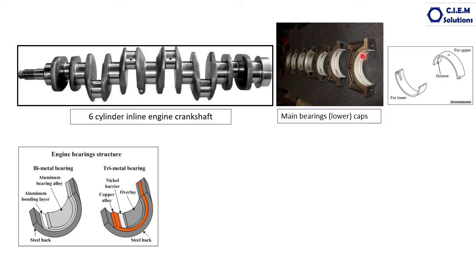These are designed like this because the crank journals or connecting rod big end are always subjected to impulsive forces. The piston fires, and the piston gives a hammering action on the connecting rod as well as the crank pin. So ball bearings etc. will not withstand, and the possibility of breakage will be there. The bearing provided here should give a proper amount of cushioning plus lubrication. This is the path for the oil flow, right?